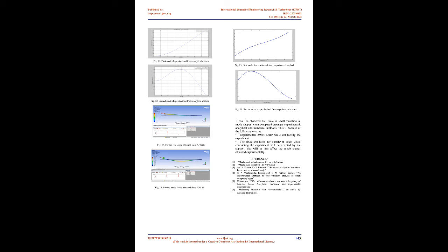In the acceleration matrix, 14 by 5, the rows represent the acceleration values at the nodes and the columns represent the natural frequencies. These values along a particular column are plotted against nodal distance to obtain the mode shape at that particular frequency.